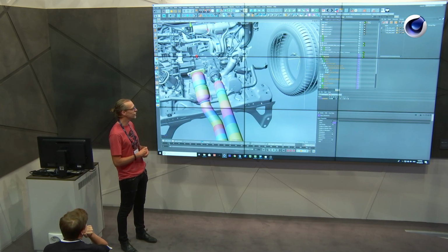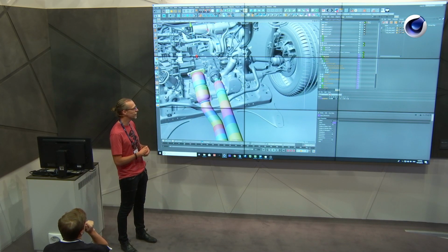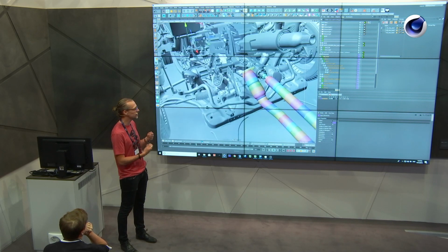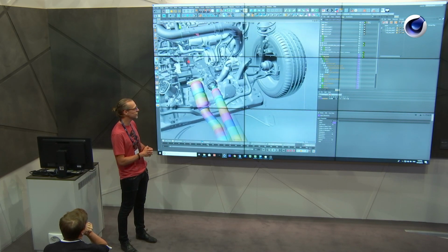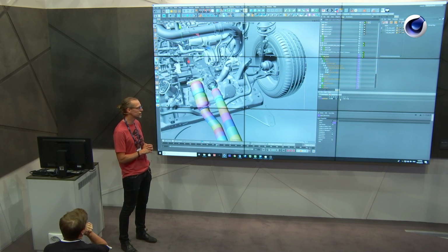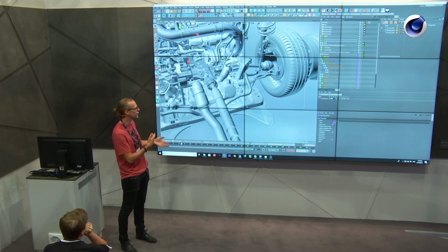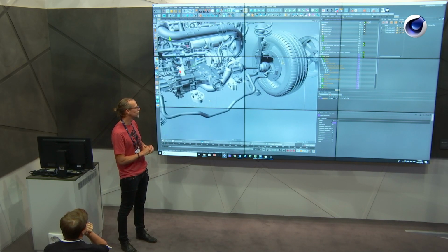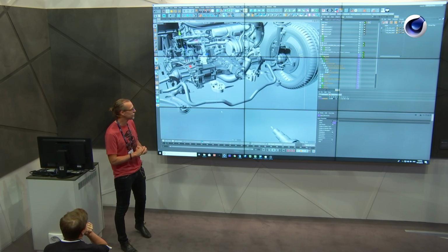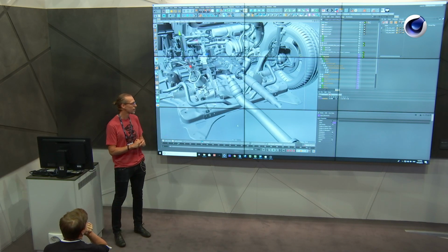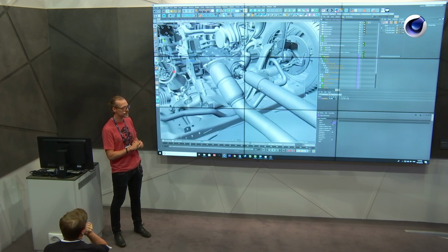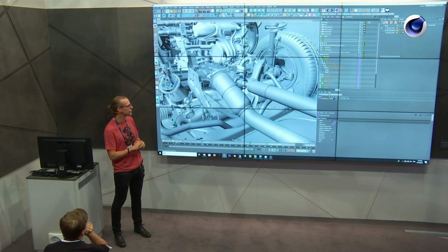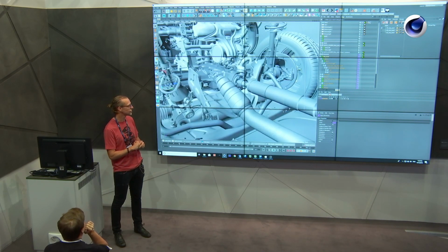But if I've added stuff into my layers, I can filter out, just showing the keyframe animation this time. Likewise, turning off the animation and just showing the MoGraph animation. Just running them one-on-one makes it so there's very fast feedback in the viewport. So layers make it so that you can work very, very smart inside of Cinema.